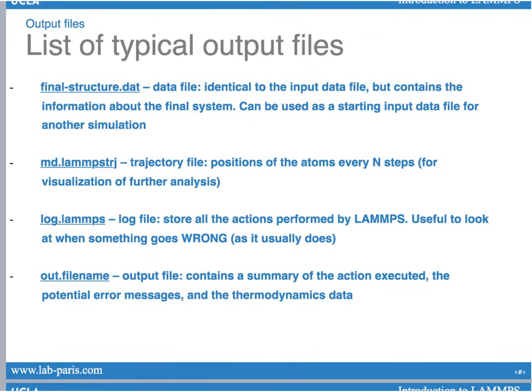If the simulation is stopping, if there is an error message, it is in this file that you will first find the error message and try to understand what went wrong. Why did the simulation stop? Why did you not get what you expected? It is in this file that you will find all the useful information that can be used to try to debug the input file. The last file is the output file.